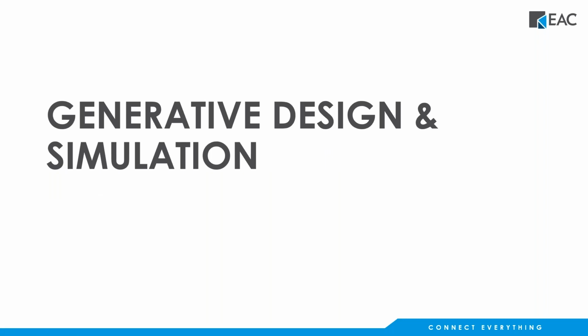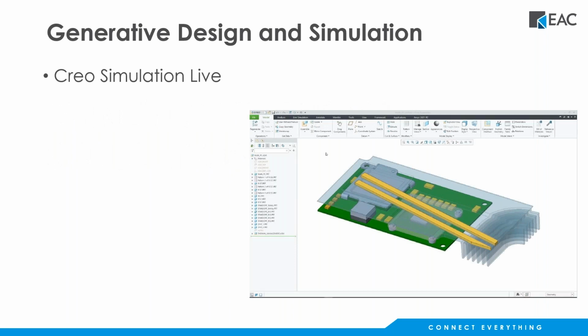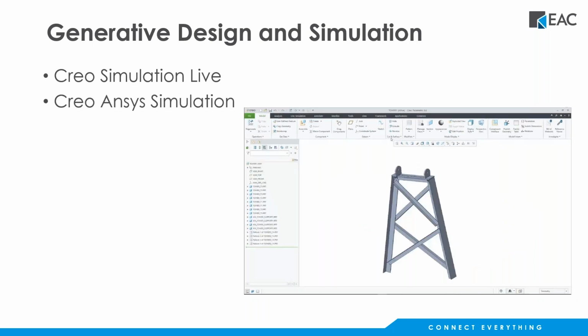All right, next we're going to be talking about generative design and simulation. So there's been a few updates with Creo 9 in terms of our different generative design and simulation tools. And starting with Creo Simulation Live, we now in Creo 9 support multi-physics with thermal and stress loads. And we can now include gyroids and lattice geometry in fluid studies. For Creo ANSYS, we now have an automatic mid-surface geometry. We have added support for bearing loads. We can now simulate unconstrained structures, which is something we've never been able to do before inside Creo Parametric.